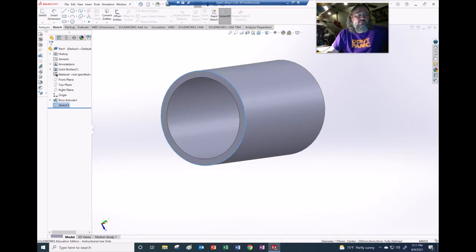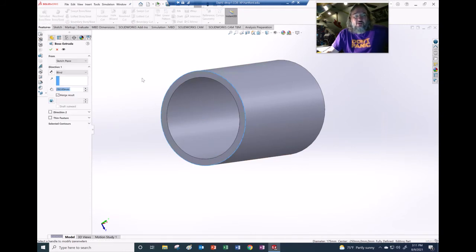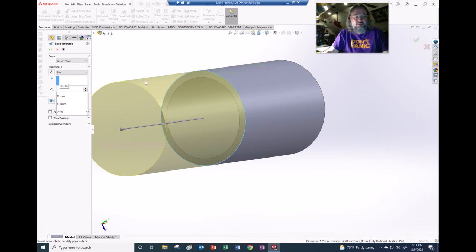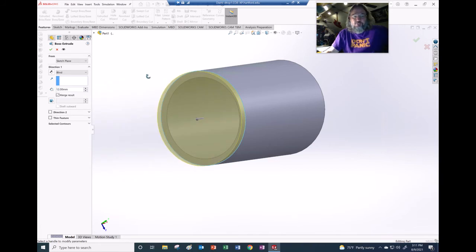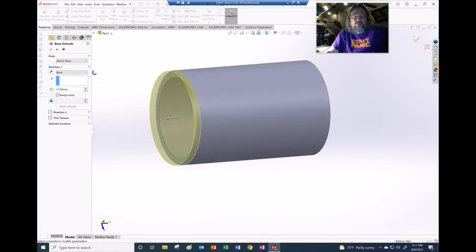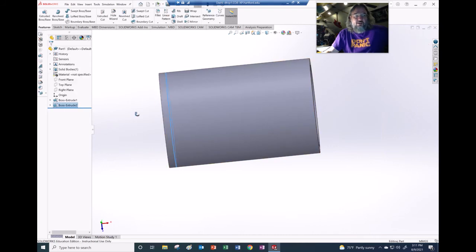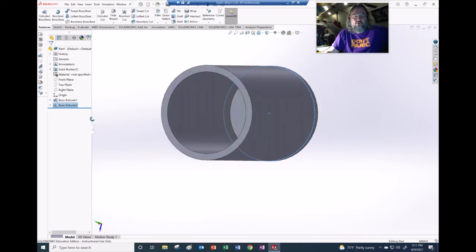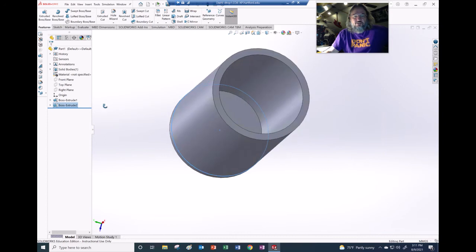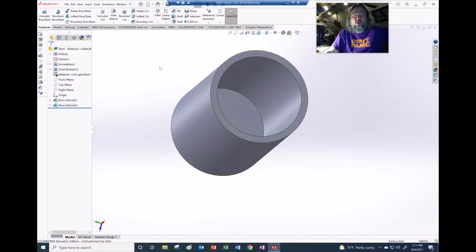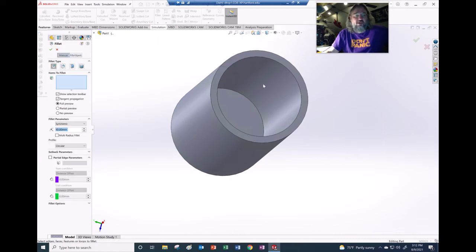And then, so I'm out of that. I'm just going to extrude that by just the thickness right there, right? Boom. So now I've made the thing. It's 12 millimeters thick everywhere. And I'm going to try to avoid some of those stress concentrations. We're going to talk more about what a stress concentration is, but they show up in FEA all the time.